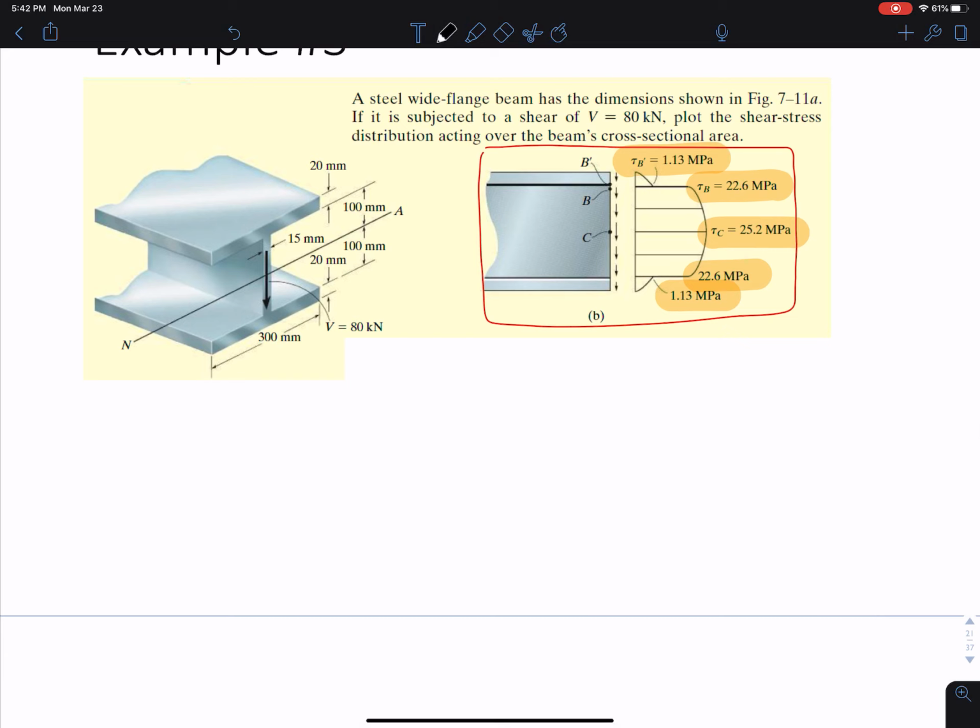What we would know is the cross-section. This is the cross-section of the beam. And if we want to see the whole beam, it would look something like this. And then we'd have those top parts for the flanges, kind of curved. Okay, and then we'd have some cut here, and we have this shear flow, and we know that the shear flow varies parabolically, so it gets bigger, bigger, then smaller, smaller, right? Okay, and if we wanted to plot this, it would look something like this.